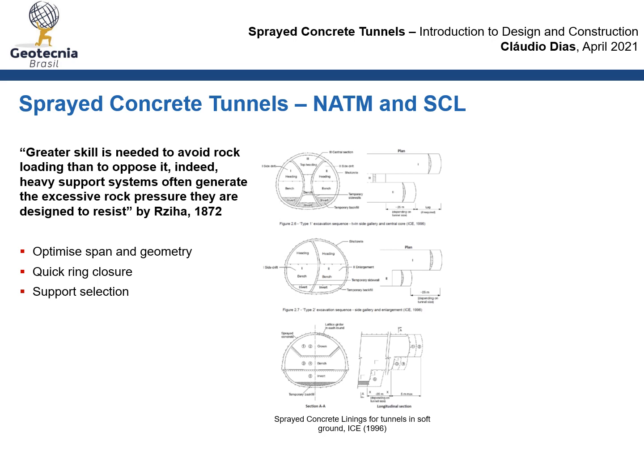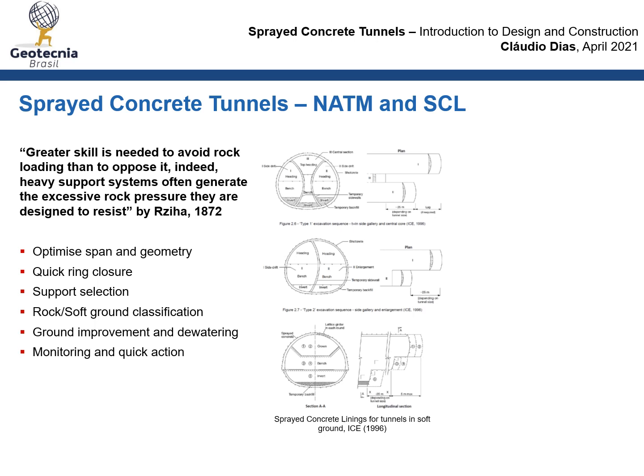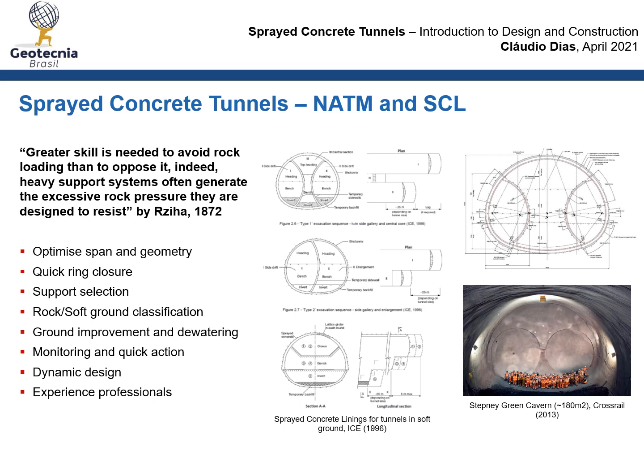The support selection is very important as well. Rock and soft ground classification to make sure we have different supports for different classes of the ground that the tunnel has to go through. Ground improvement and dewatering whenever necessary to support the excavation. Monitoring all the displacements to make sure we can have a quick action. A dynamic design and using experienced professionals.